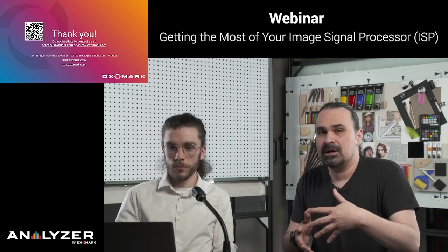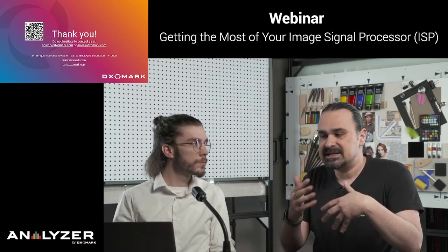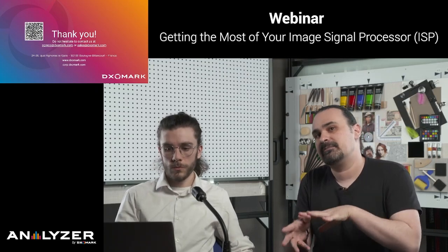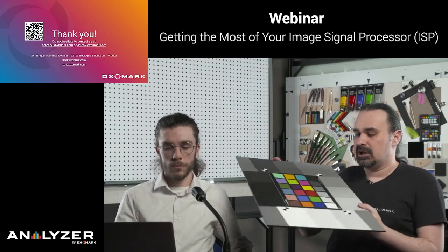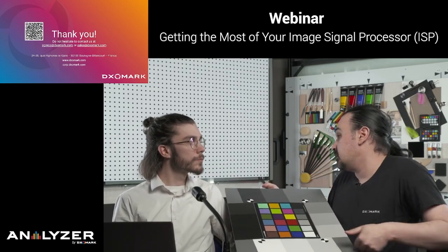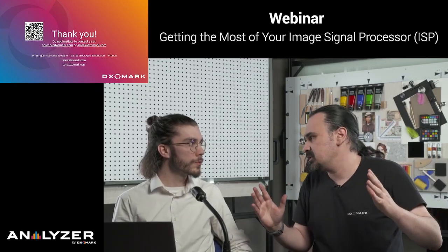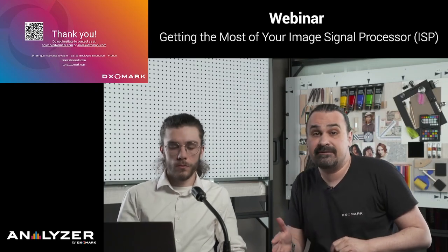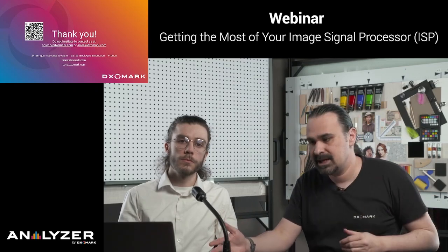Similarly, you can do that if you decide on a certain thresholding of compromise between how much vignetting you correct and how much noise you get. For our noise measurement that I have done on this chart, with the Workflow Manager, you can put a uniform region of interest wherever you want. So you can do it on a gray chart. You measure on the same picture taken under different lighting conditions, so for different lux levels from 0.1, 1, and so on and so forth, up until 10,000 if you need that.